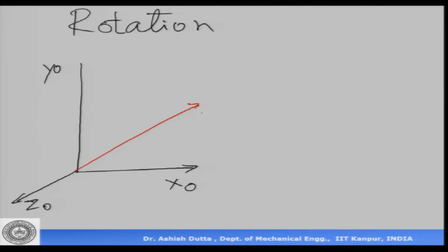Let me call this my x1 as I have drawn in the two link manipulator system there, and this is my y1. Then if I have a point which is here, let me call that point BP, and BP basically means the point is P and with reference to frame B. So this is my frame B, this is my frame A, right. So when we say coordinate of this is UVW, it basically means this is the distance of this point projected on the x-axis and the y-axis, so that's my u, v and w.